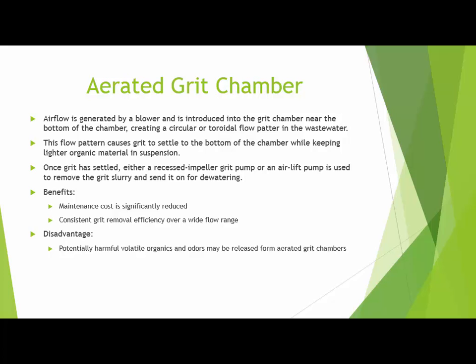Some of the benefits of the aerated grit chamber are that the maintenance cost is significantly reduced compared to the other two types of grit chambers, and you get consistent grit removal over a wide range of flows. One of the disadvantages, however, is that potentially harmful volatile organics and odors may be released from aerated grit chambers.